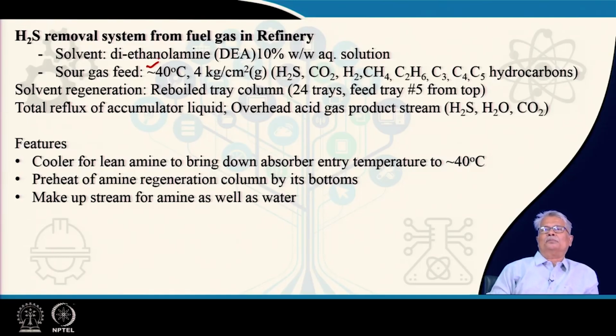Typically, H2S and CO2 are not highly soluble in water or in the aqueous phase. But if you have an alkanolamine solution, in this specific case diethanolamine or DEA, a 10% aqueous solution as a solvent, the solvent consists of two things: water and 10% by weight of diethanolamine. Together they have high affinity for H2S and carbon dioxide.